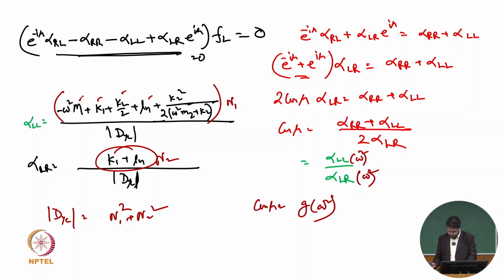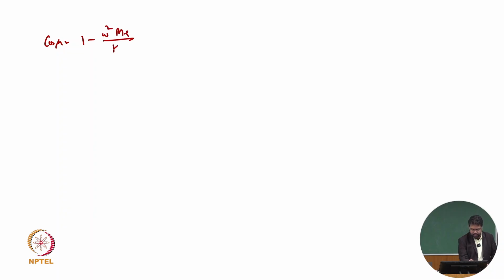And after that, if you go ahead, so here actually, why do we do all those things, and what can we get from here? We can write the dispersion like that, cos mu. One important thing is that cos mu can be written as 1 minus omega square into effective mass divided by effective stiffness, that we have seen in the last class, or in the previous classes. Once we have the effective mass and effective stiffness concept, we can write the dispersion relationship in terms of them.